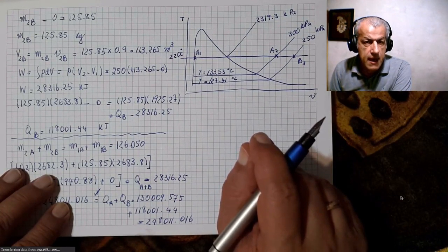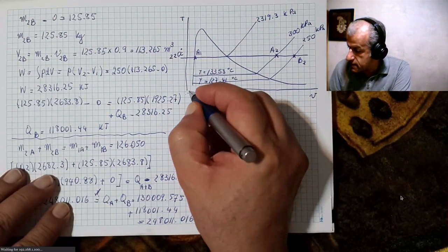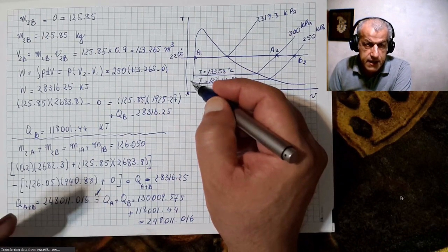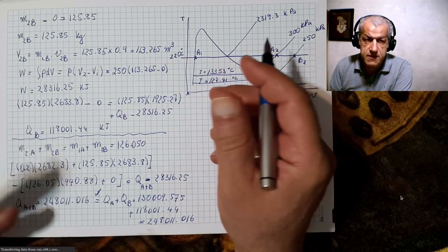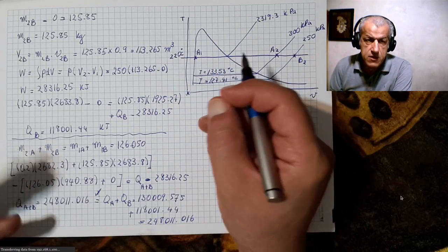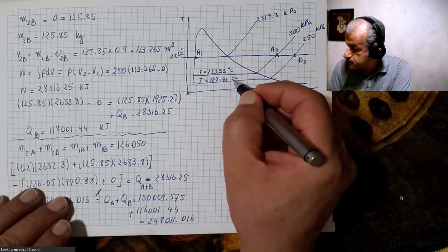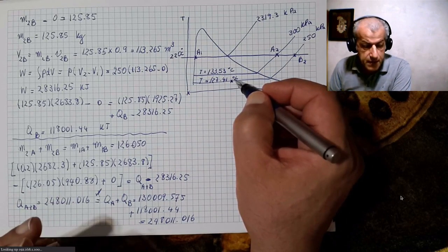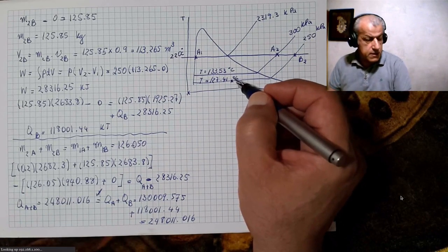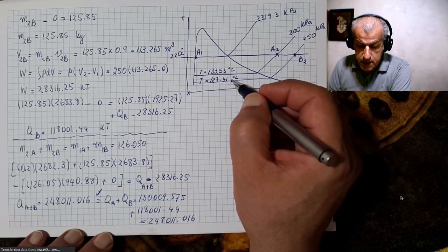Where is the initial point at B? Well, certainly, as the volume is 0, this is a good candidate, but look, there's nothing in there, so any temperature would be irrelevant because there's nothing in B. But the first mass that enters B is at some point here, where we assume that at that point the H would be 1925.27.